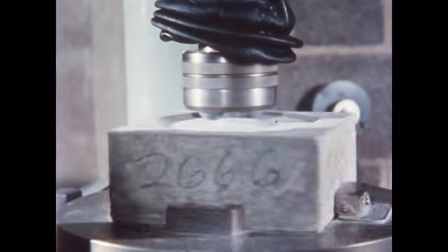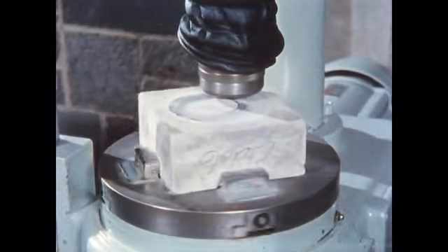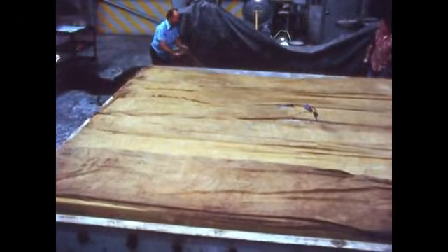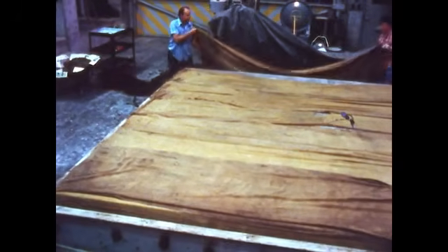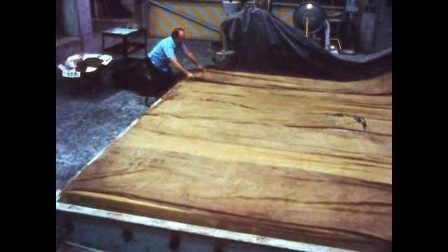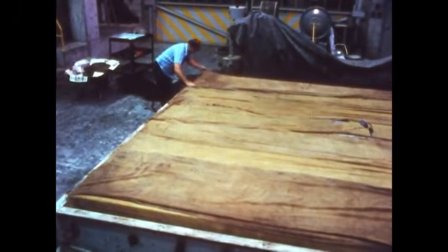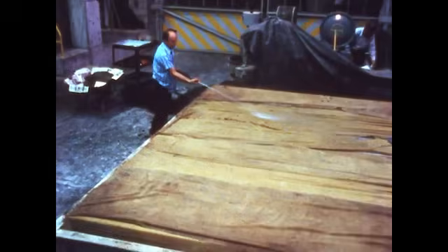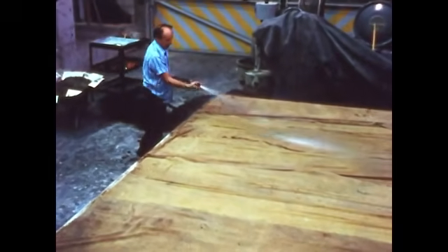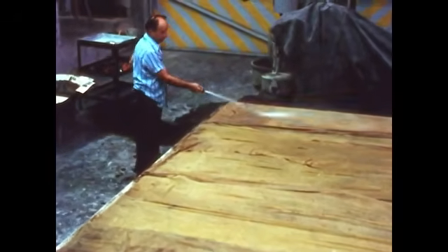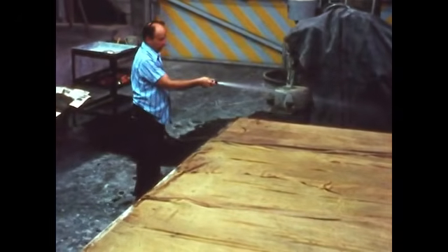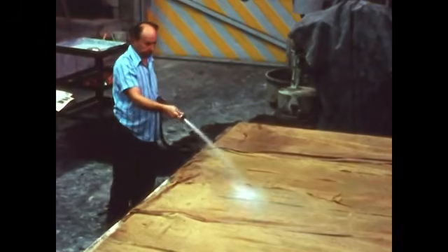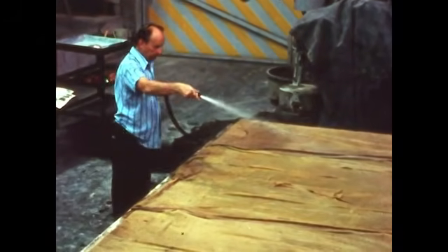Concrete made with only 0.45 pounds of water per pound of cement survived the test with little wear. The strength of concrete at any water-cement ratio is improved by increasing the curing time. Concrete is cured by being kept moist at reasonable temperatures for as long as it is practical. As long as moisture is retained and the temperature in the concrete is favorable, the cement will continue to hydrate. Tests made at various ages show that concrete will continue to gain strength as long as it is cured.